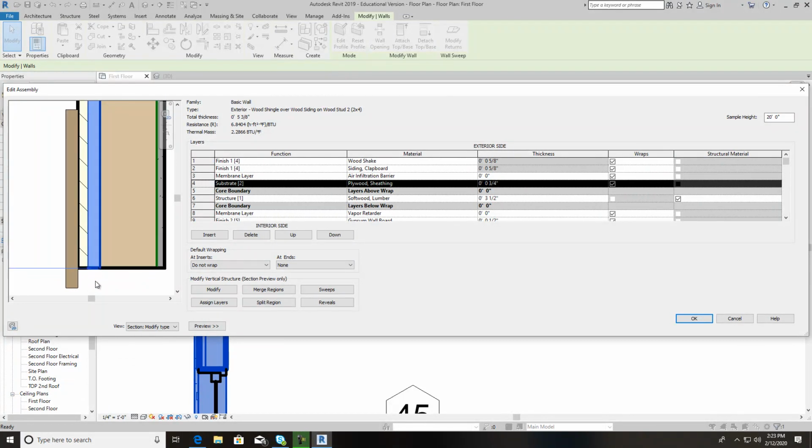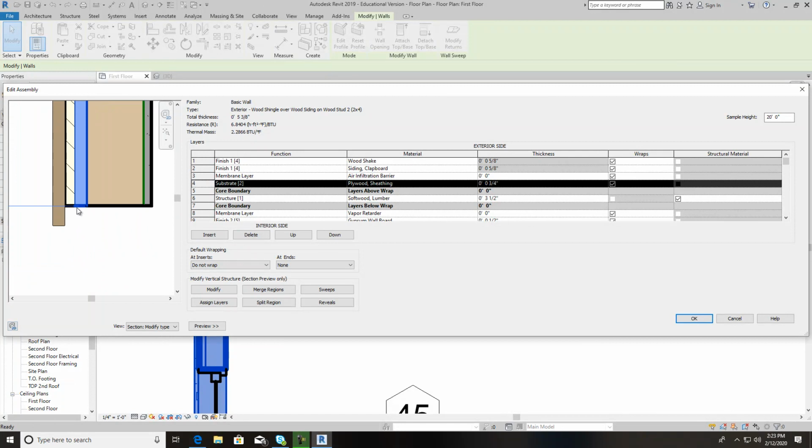Well, down here, your concrete would basically be running, or your concrete masonry units, like your block or your solid concrete, the edge right there would be where that block would be. And let's say coming straight down here would be your block, and it would be going over and up. Now this right here would actually lap over that just a little bit, so when it rains, the rain comes down and it goes right off.